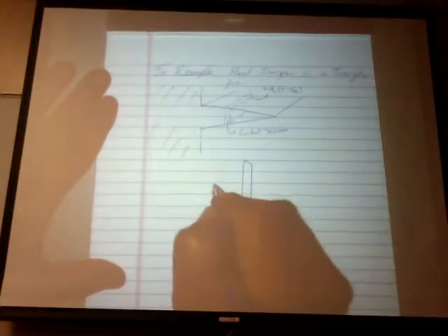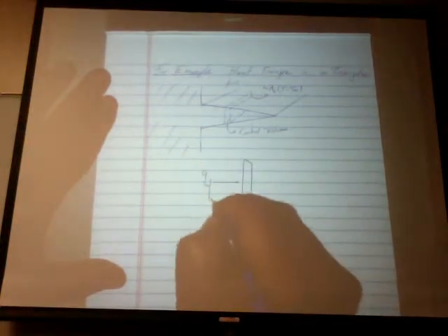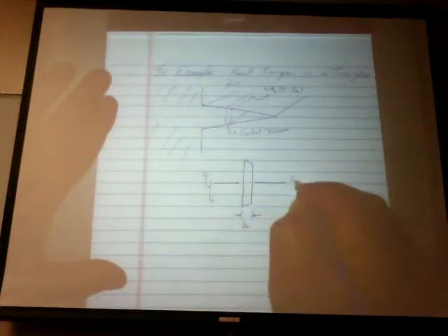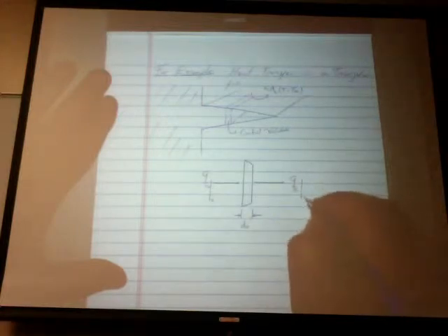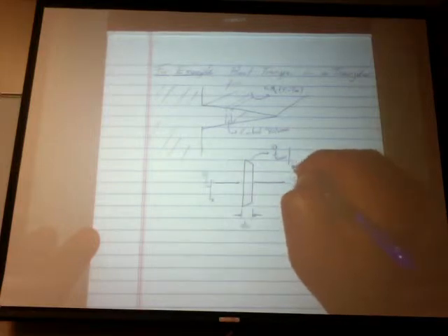And when we have Q through conduction going in at x, this is of size dx. We have Q of conduction going out at x plus dx. And then on this wall, we have convective Q going on the periphery.